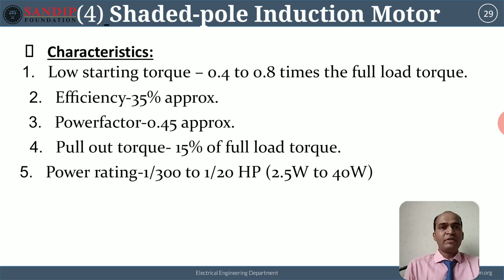Induced EMF and flux phi s are negligible. The resultant flux is almost in the center of the pole, thus has shifted its position. At the instant T3, the current is decreasing. The induced current and flux phi s try to oppose this decrease. Hence, there is a crowding of flux in the shaded part, the resultant lies in the shaded part, and the motor rotor starts rotating.